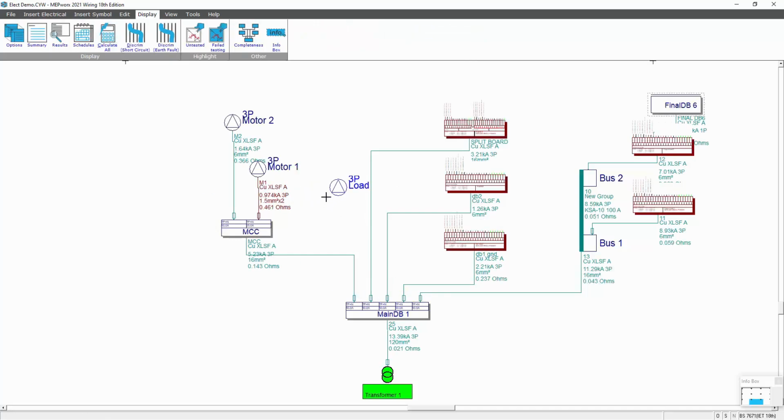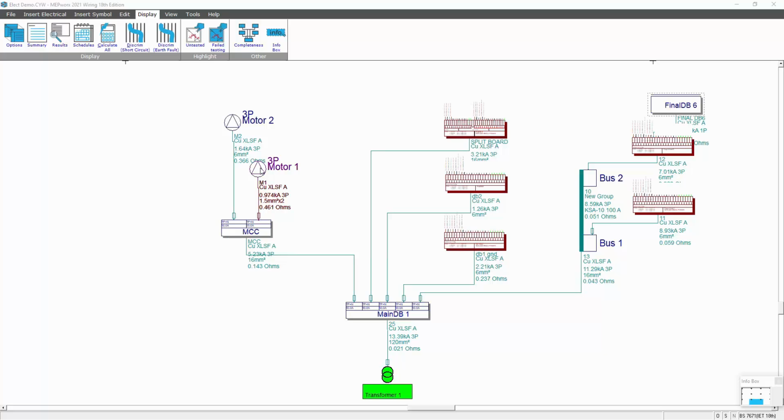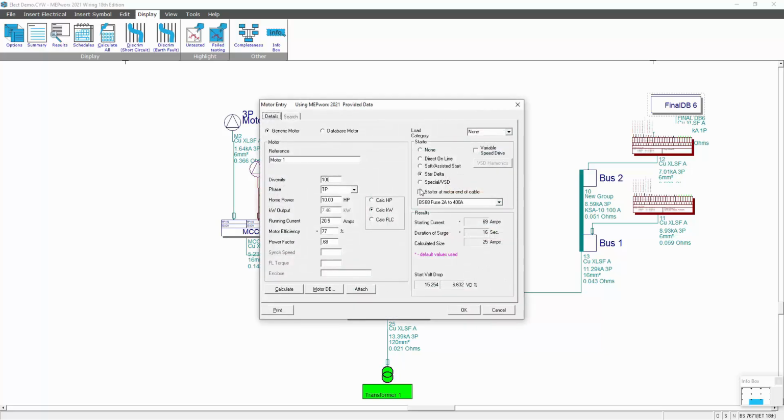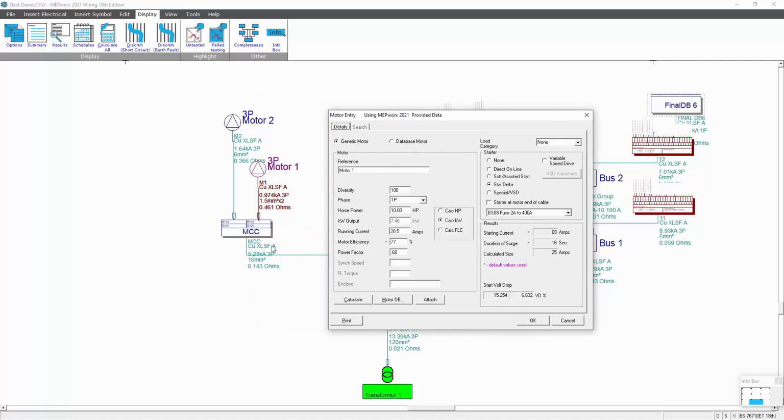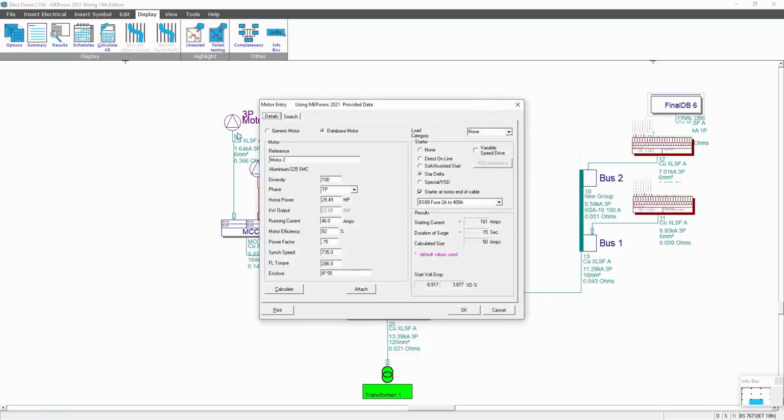you can see here, on this particular motor, because we've gone into the motor details and we've put in the starter at the motor, basically in the box in the MCC, you're running those cables into the motor and out and back. So you've got 1.5 mil times 2. But on this one, we have the starter at the motor end of the cable. So we're just running our 4-core cable out to that motor.